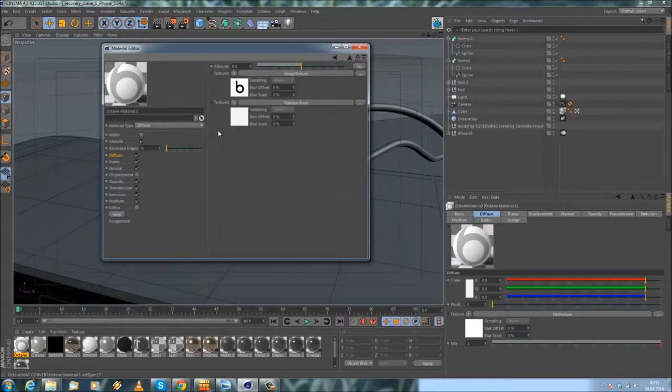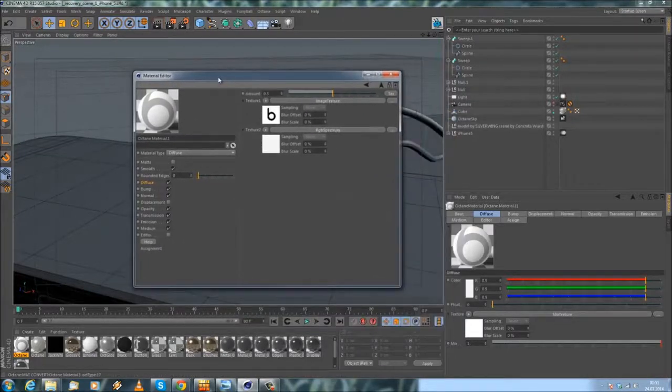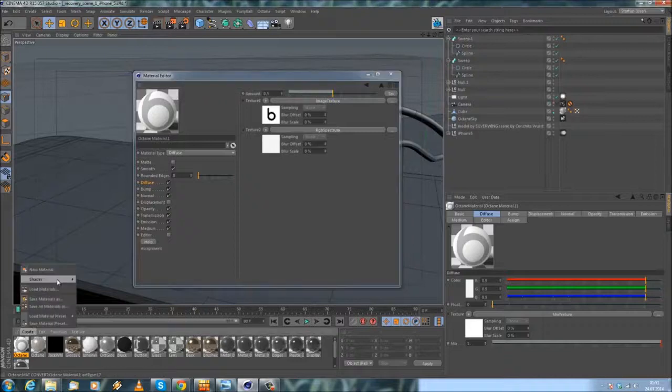And the red Beats logo itself should be something like red plastic and the background should be brushed metal. So we do exactly the same thing that we did with the Apple logo on the backside before, so that we have 2 different colors. The only thing this time is we also need to create a mix material, because otherwise it would be impossible to mix 2 different indexes together. Plastic has something like 1.5, the metal has probably something between 3 and 8 of an index, and we can't do this in one material, so this is why we will use the mix material for that.